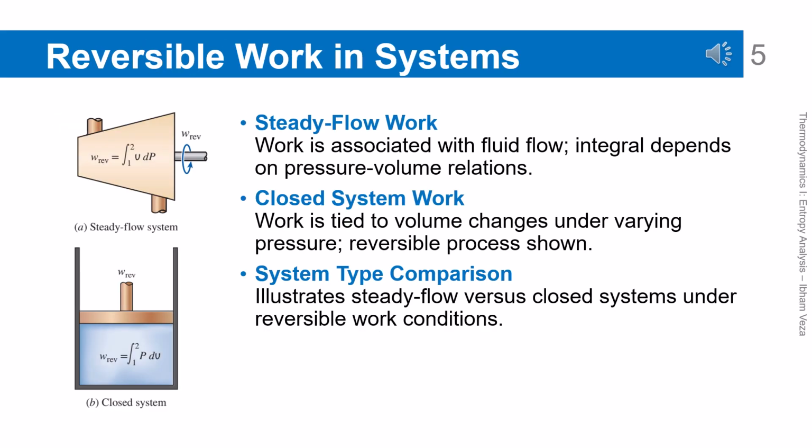Reversible work in systems. The concept of reversible work is introduced for both steady flow systems and closed systems. In steady flow systems, work is expressed as the integral of VdP, which depends on the pressure-specific volume relationship. In closed systems, work depends on volume change under varying pressure.